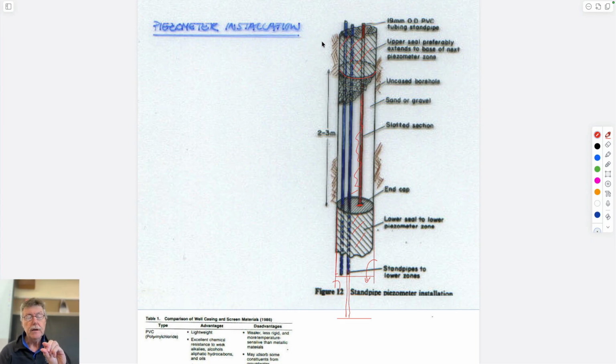They're little compressed aspirin almost, right? With a varnish on them. They drop down to the bottom, the varnish dissolves, and then as they take on water, the bentonite, as a swelling clay, expands and seals the borehole by closing up all the holes.